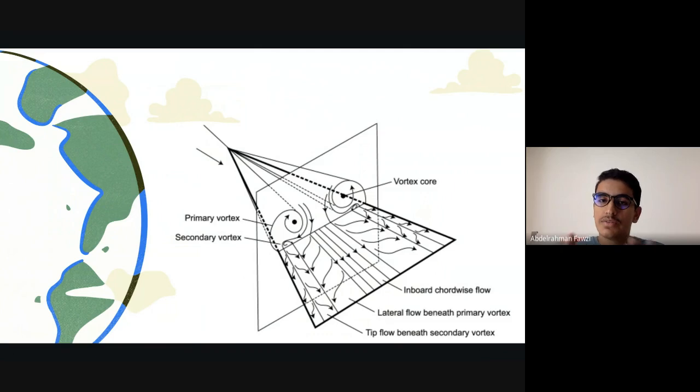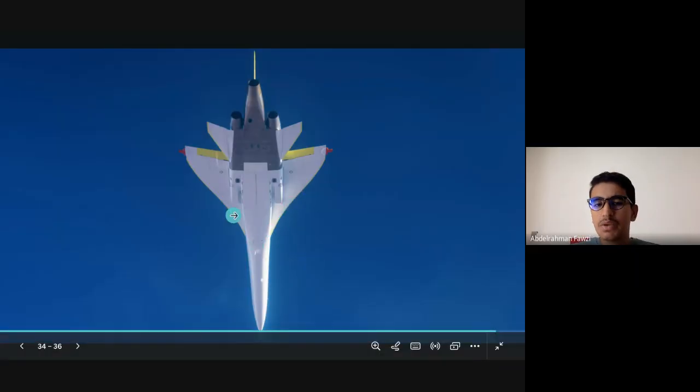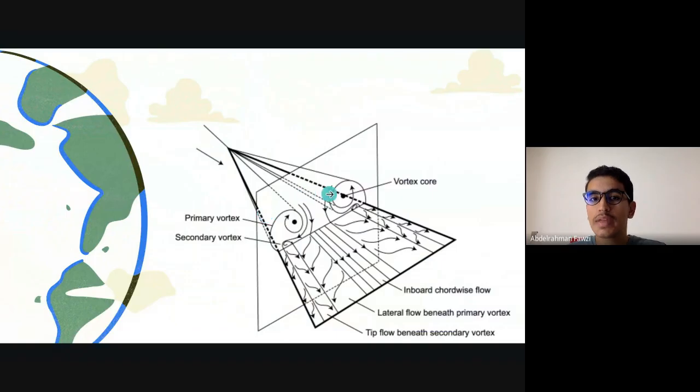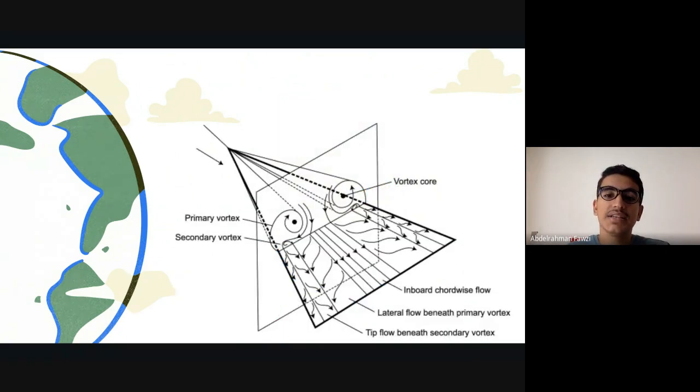The lift at lower speeds, in landing speeds or takeoff speeds for example, is going to be low. So we try to create these edges in a certain way that causes a vortex to happen. As we know, the vortex is literally the translation of friction; the amount of energy that you lost is going to be transmitted to the air, and the air is going to have lots of kinetic energy, meaning that it's going to be fast, which yields lower pressure, even lower pressure on the wing. So this is going to enhance the lift at the end.